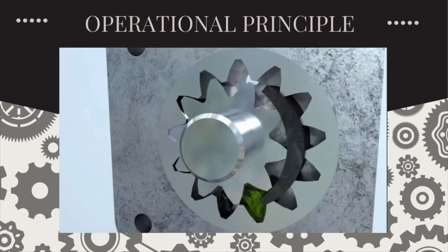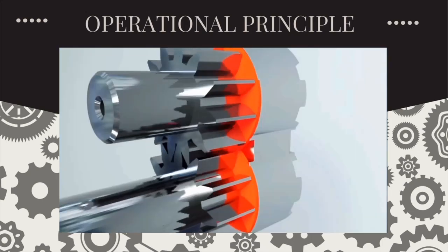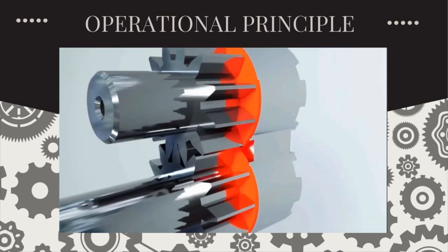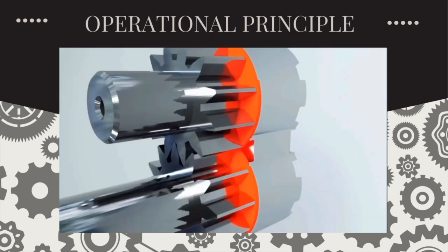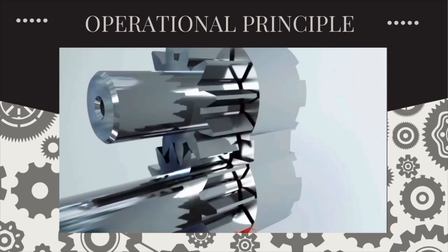And lastly, what problems can occur during gear pump operation? Bearing wear. The material of the gears is harder than that of the bearing, and so the bearing will wear out faster during operation. Bearing wear can cause increased leaks inside the housing.